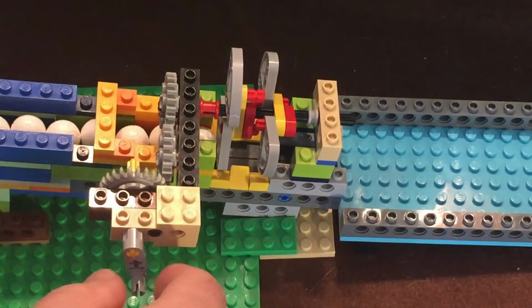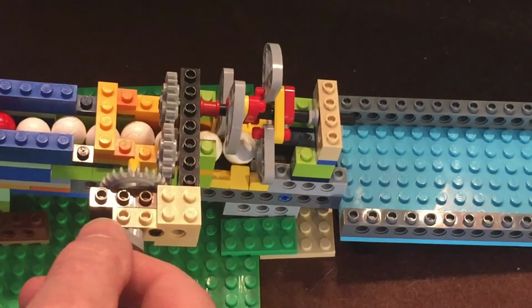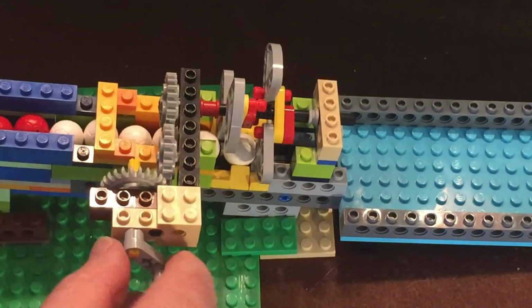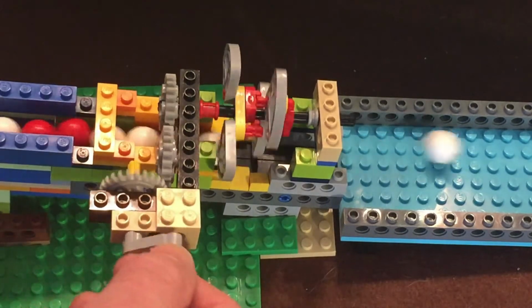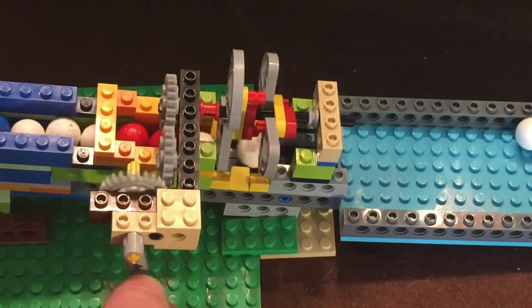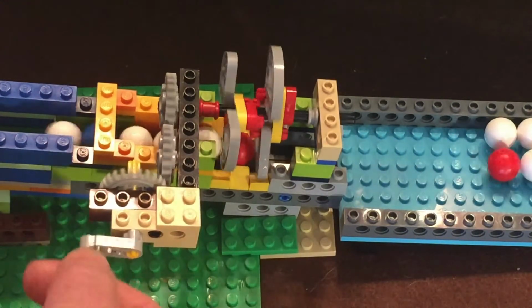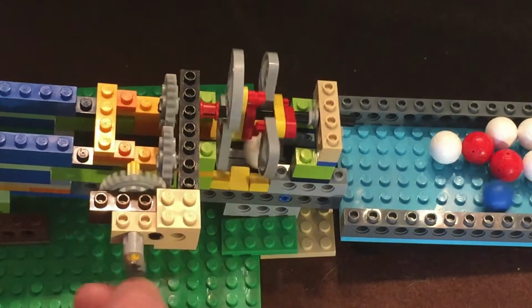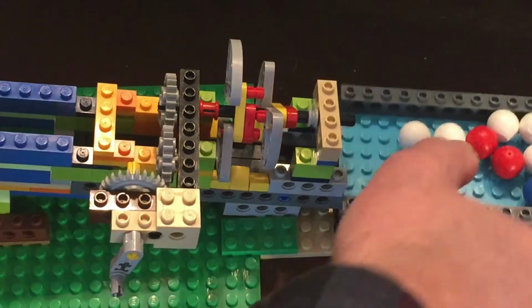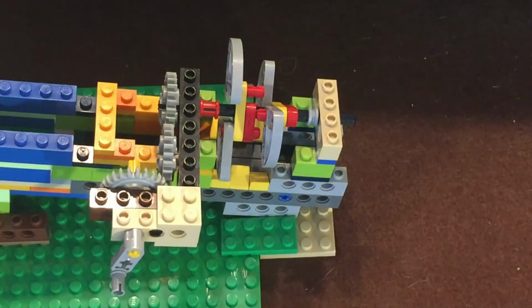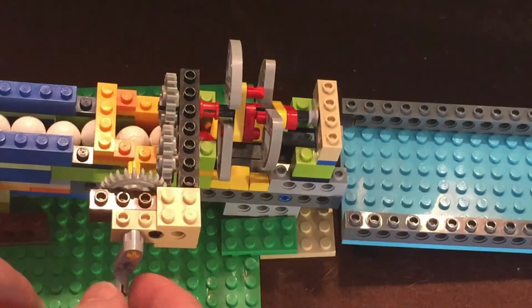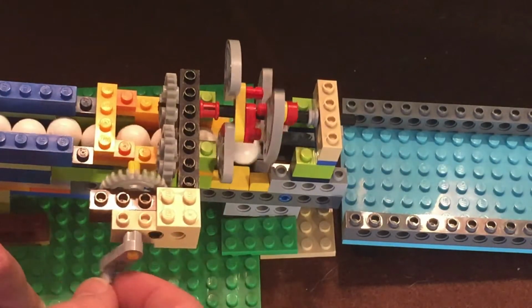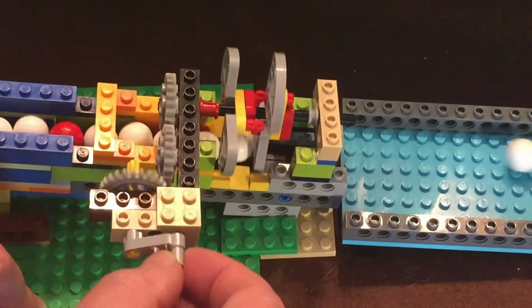My next design is this one. It uses rotating blades to do the same thing as the previous design, except the blades move in a circle instead of up and down. You can see how the first gate lets one ball through at a time, because that ball will be stopped by the second gate. By the time the second gate opens, the first gate is closed, so only the one ball can advance. Note, because there are 2 slots in each wheel, the spacer will pass 2 balls per revolution rather than just 1.